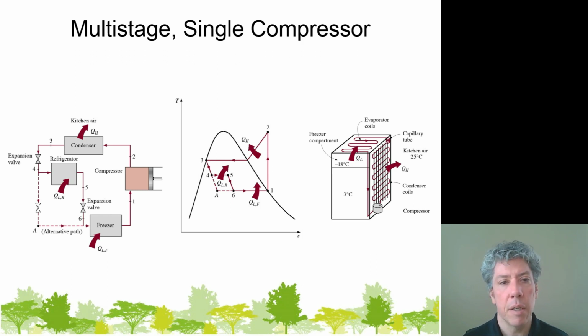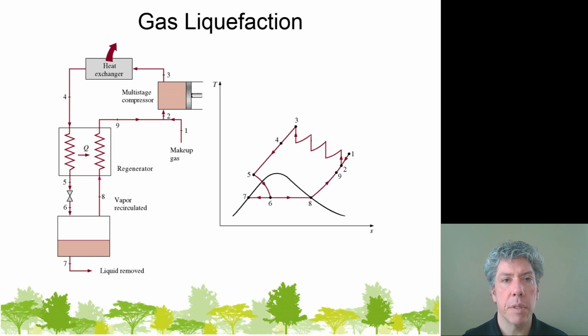A456. Do you see that area? QLR is shown there. It's coming in from state 4 to state 5. That area represents work that the compressor does not have to do. And so it's not as good as either of the two former ideas for increasing the efficiency, but if you don't have a real large temperature difference but you need two different temperatures, here's one way to use a single compressor and get some extra energy savings out of it. So this is actually fairly common on refrigerators these days.